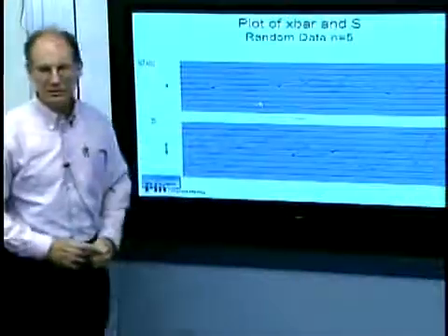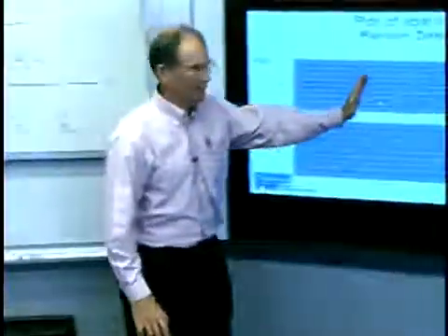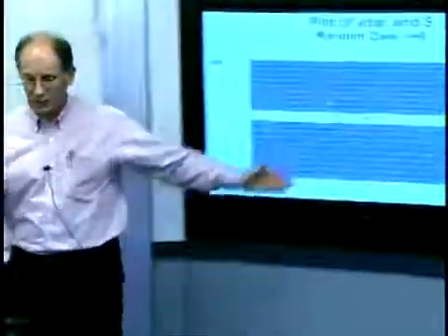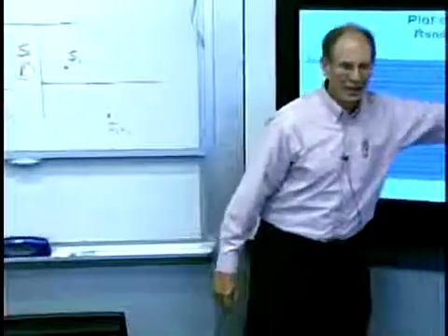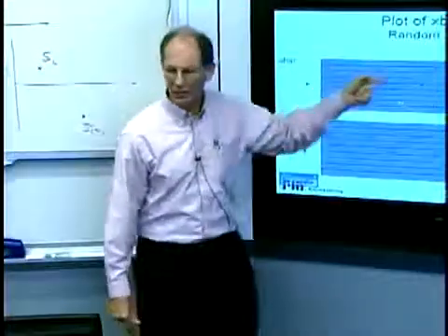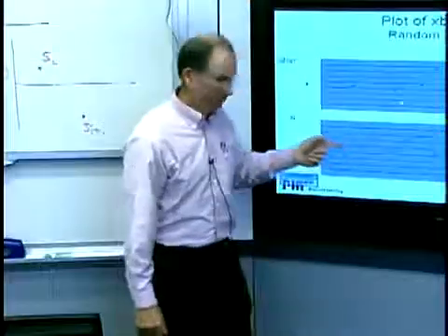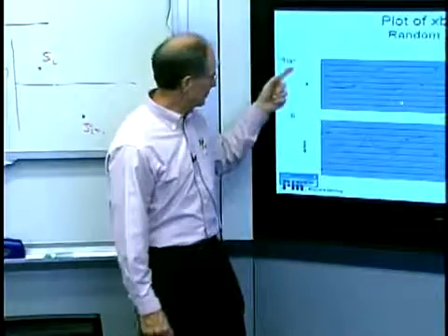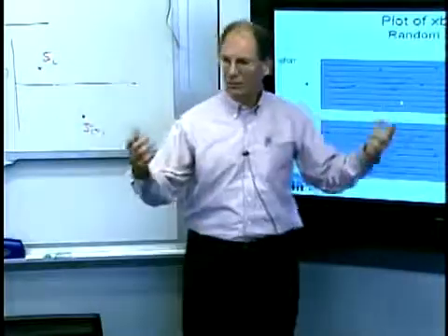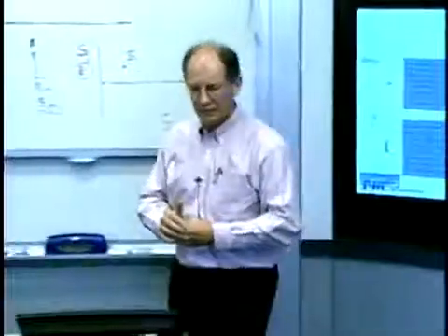And again, I can look at its average value. So this is what you get. You plot a new data point, and this is what you start to expect. Now, of course, I can look at this and get a grand mean, which is an average of all the average values, and a grand standard deviation estimate. I should say a grand average and a grand standard deviation estimate. And say, okay, now I know the underlying distribution of the process.